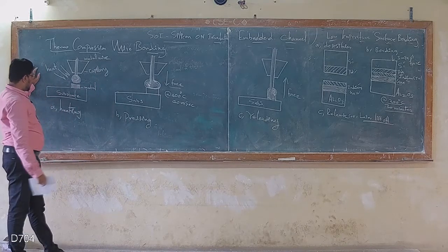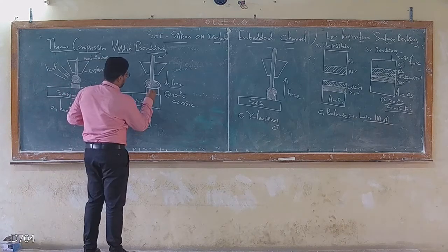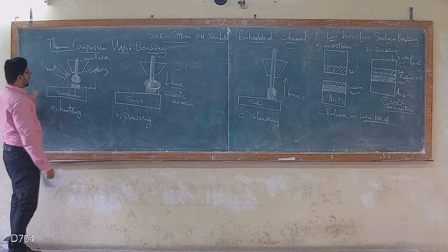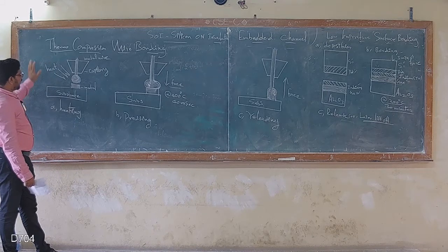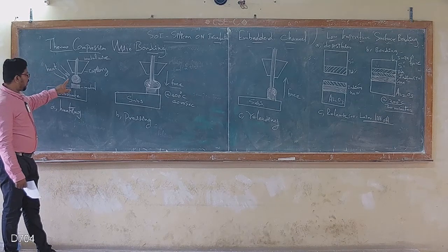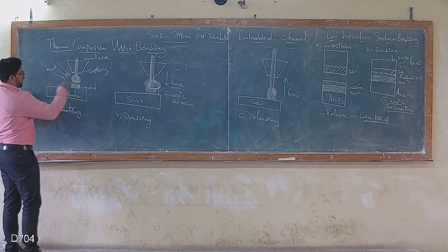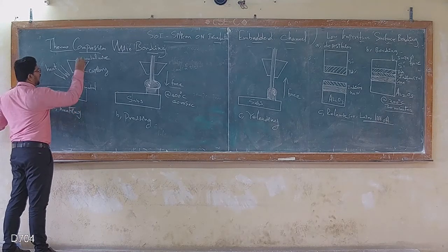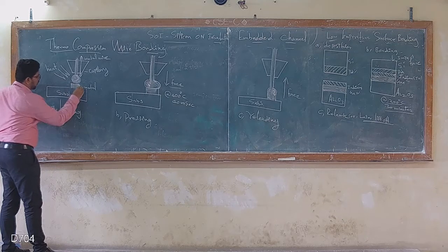Thermocompression wire bonding. It has a substrate, and the substrate carries metal patches. The substrate could be a PCB. We are going to make an electrical connection with the help of the thermocompression technique. As I mentioned, what do we mean by thermocompression? We are applying the necessary heat to melt or to make a bond of the metal as well as the bond head metal. This is carried by a metal wire capillary, and as an action the wire can move down and up, because we need a movement to make sure of the metal connection. So this is called the heating process.